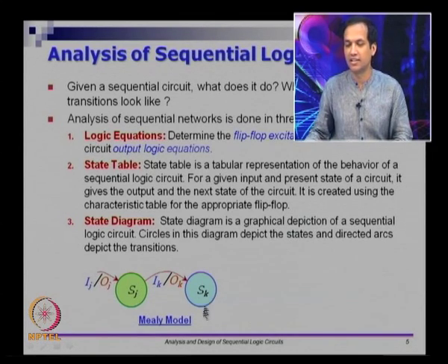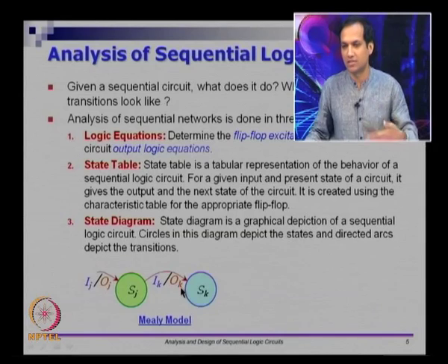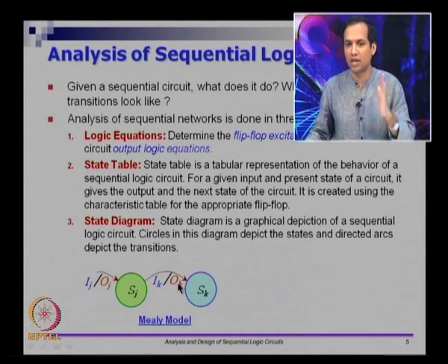So each state is marked with a number Sj, Sk and so on, and the meaning of this part of the circuit is if the current state is Sj and on getting some input Ik, it will go to the state Sk and produce an output Ok. So the current state input combination drives the circuit to state Sk and it should produce Ok as the output.